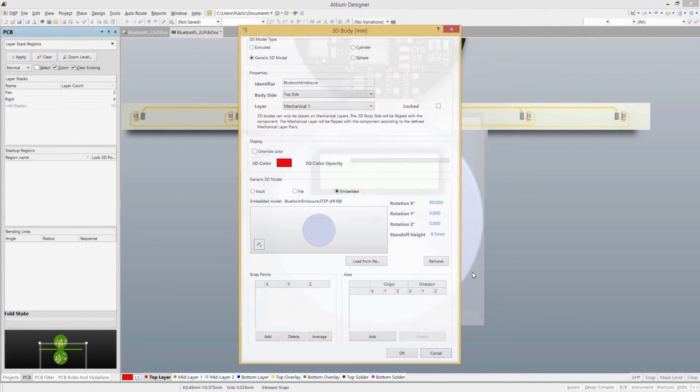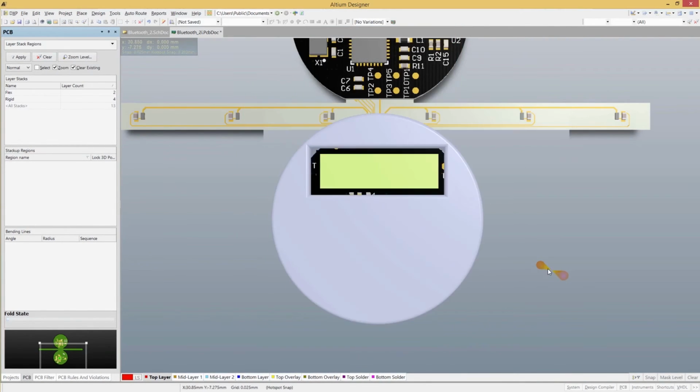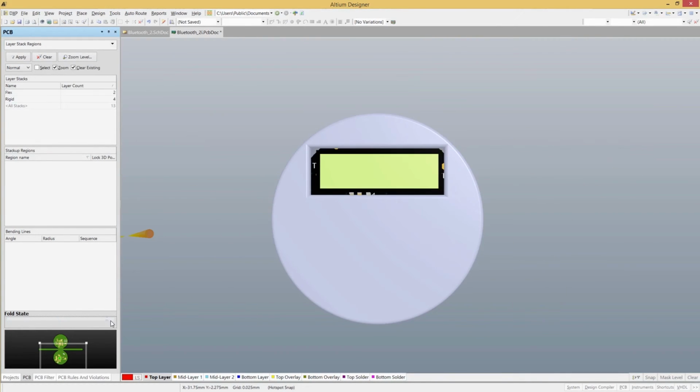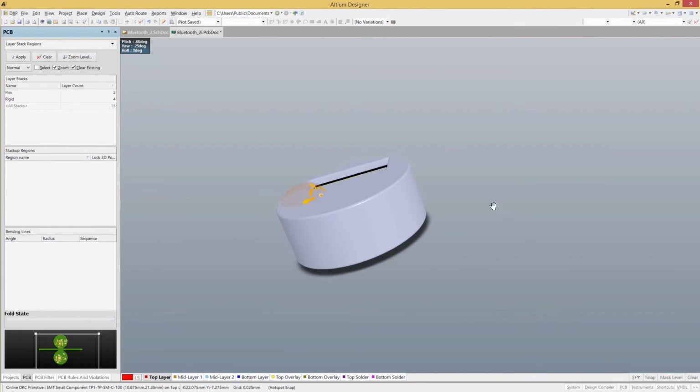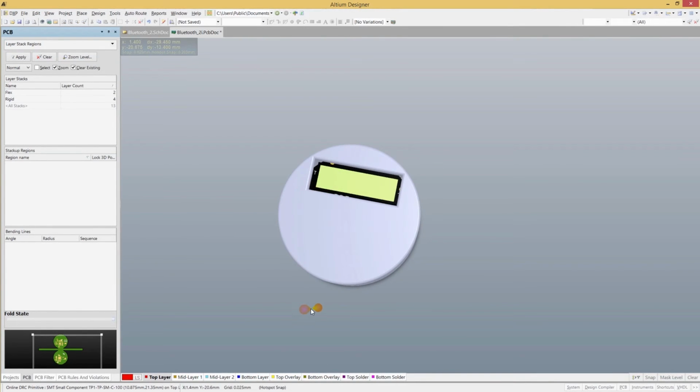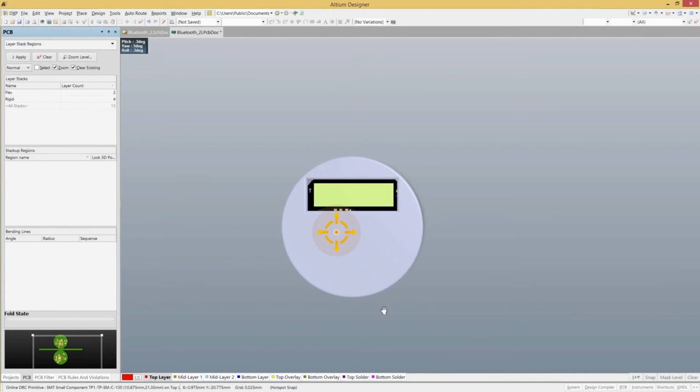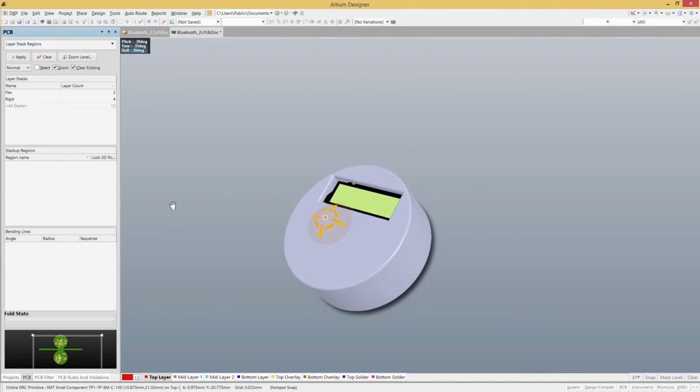mechanical considerations. Now look at this, we can go ahead and lock it to a particular point and it folds up directly within that environment. We have a true fold state of all of my rigid-flex design, in which this actually is. It fits within here, we get no green errors, and we get a good fit check of everything. Everything is beautiful.